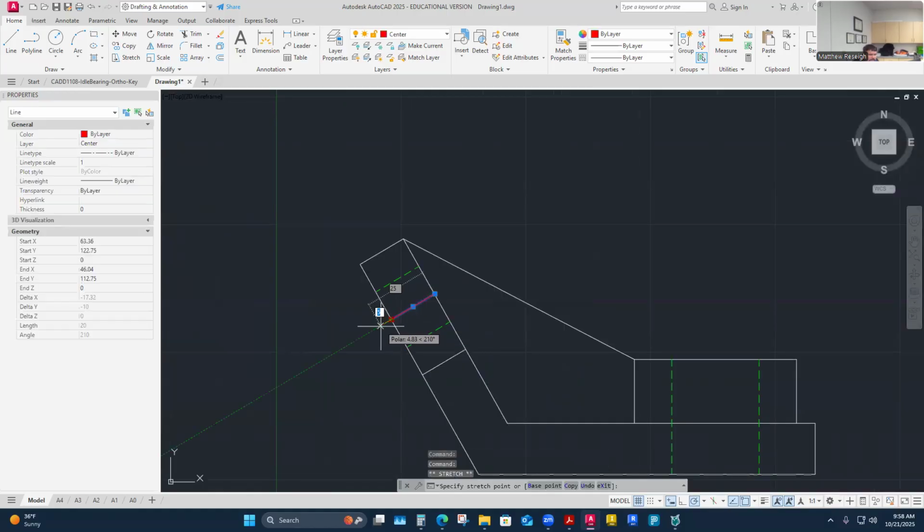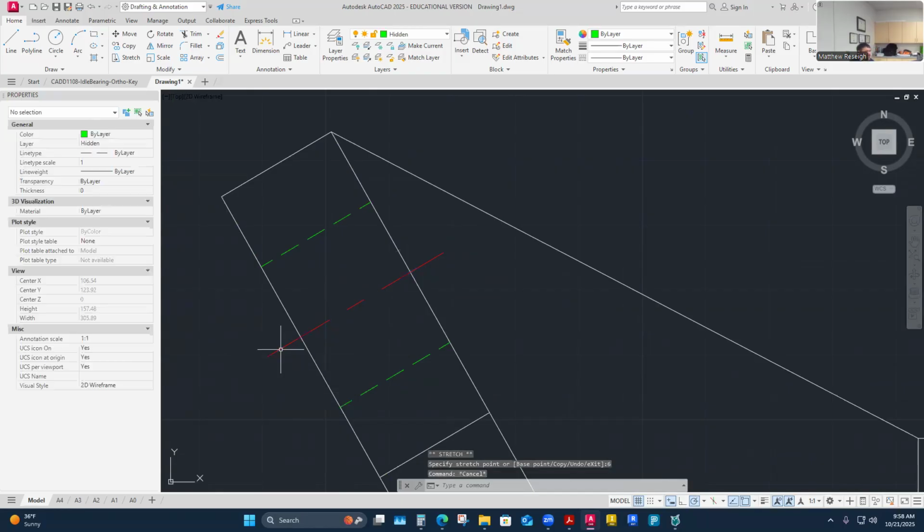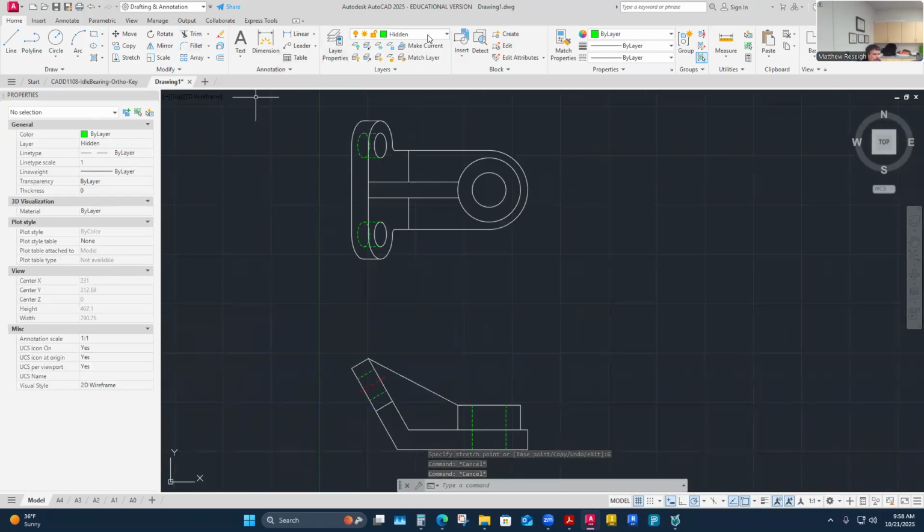This little center line needs extended by at least 10. Is that right? 10 millimeter, right? 6 millimeter. Good call. Not 10. 10 would be how far I would space the dimension. Yeah, quarter inch is essentially the equivalent. Yeah, so that's like that. And then we'll do some more center line work, I guess.